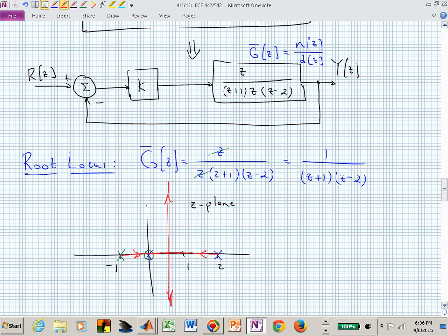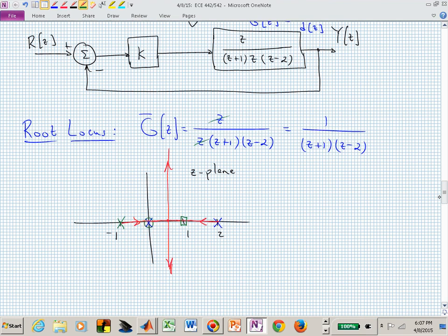And what's the lower limit on k to become stable? It's whatever gain is going to be necessary to get us to that point from that pole at 2, isn't it? We need to crank up the gain to get that pole at 2 shifted into 1. And we'll learn an equation for the gain k and evaluate that at z equal to 1 to find the gain k to get us to that point. Let's not do that right now. Let me just say, though, that the range for stability, do you see, I'm not sure I want to do this, but